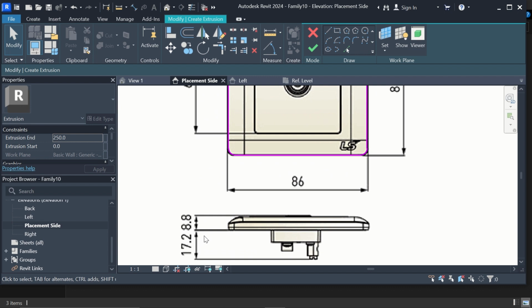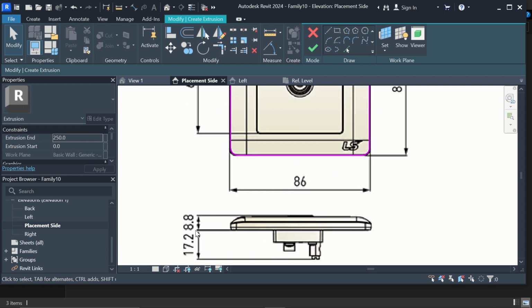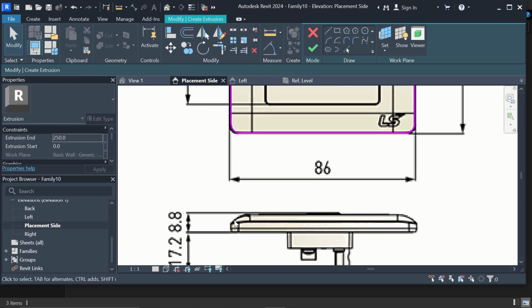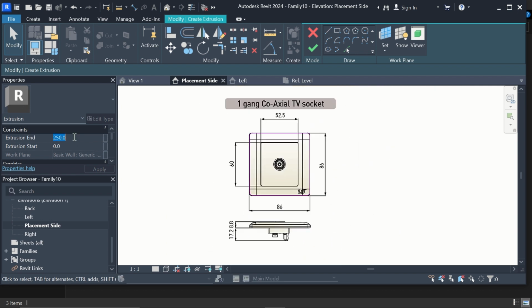So let's look at this particular extrusion here. If you notice, the entire extrusion is 8.8, but first it is done in two parts, so we're going to show it to 4.4. So to this point here, I'm going to change this part from 50 to 4.4, and we are good. So I'm going to apply it.